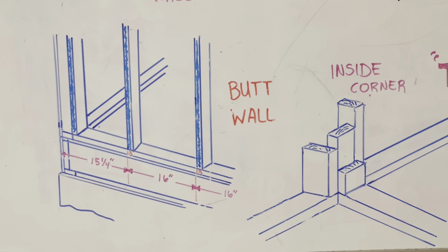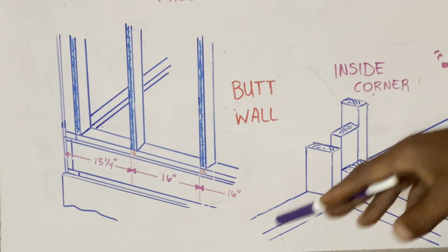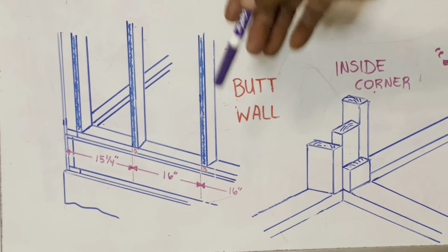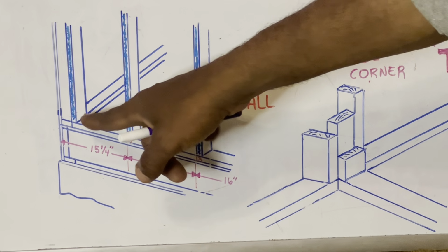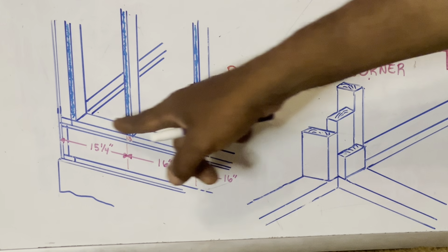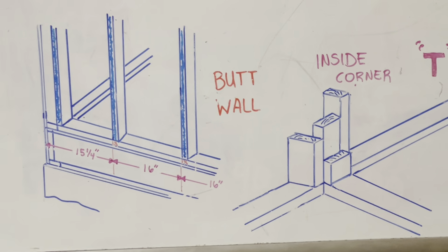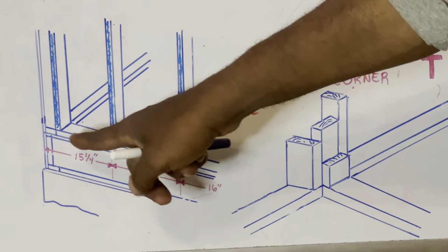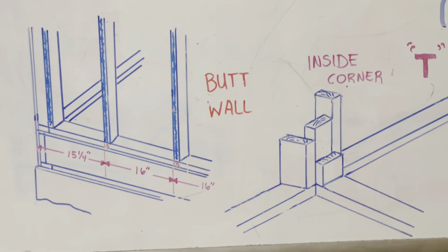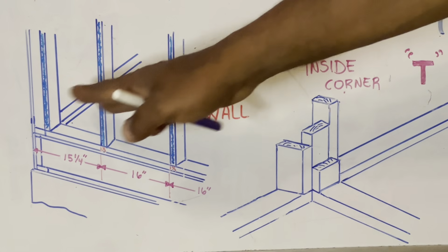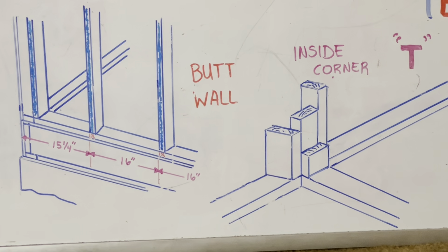So normally, how they would do this is when they're building their walls, they'll build them on the deck. First off, you would tack down your plates, maybe with some 8s. You tack both of your plates down, and then you lay out like that. Tack your plates down to the outside of your platform, your floor or your subfloor, and lay out.